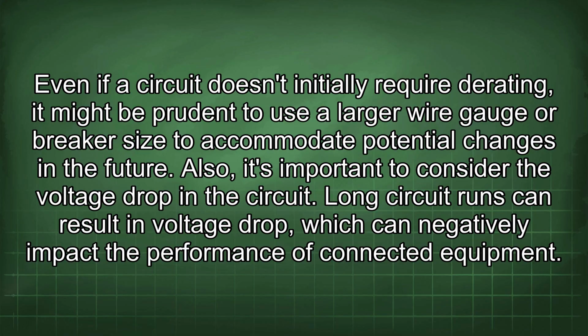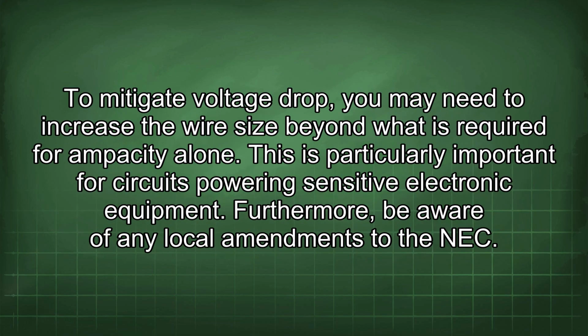Also, it's important to consider the voltage drop in the circuit. Long circuit runs can result in voltage drop, which can negatively impact the performance of connected equipment. To mitigate voltage drop, you may need to increase the wire size beyond what is required for ampacity alone. This is particularly important for circuits powering sensitive electronic equipment.